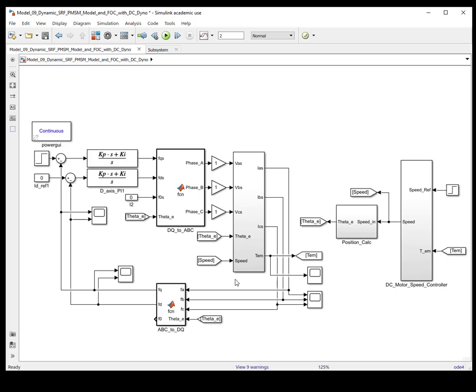Again, the way I did that here is for simplicity, because otherwise you'll have to implement a discrete time controller, then trigger it based on your PWM signal, and that adds more complexity. So to keep things simple, I've developed this basic, very simple model. But if you are interested, feel free to modify it to be edge-triggered, use a trigger to trigger these blocks, and then use a specific sample and process the field-oriented control algorithm based on that, which is closer to what the real system is doing in real life.